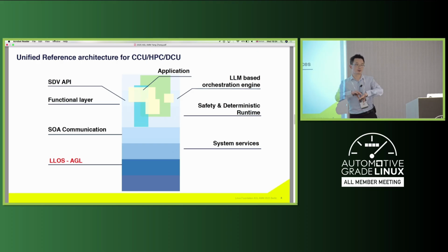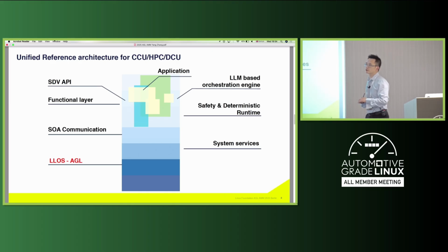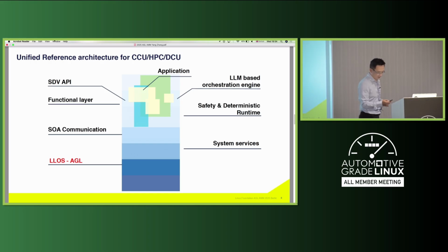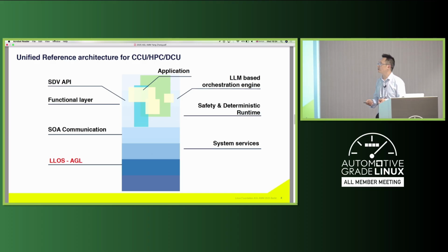Then the tasks will be separated onto each different controller, where they should go, and what type of functional safety requirements and stability requirements those services need. This turned out to be a very effective resolution for handling mixed criticality workloads on the same piece of hardware or silicon.